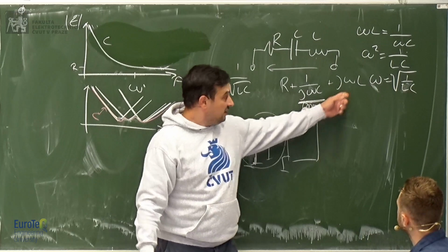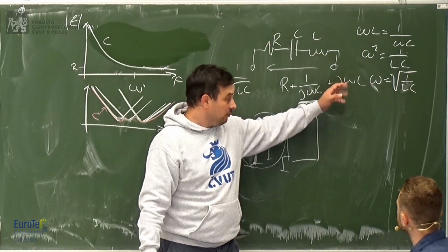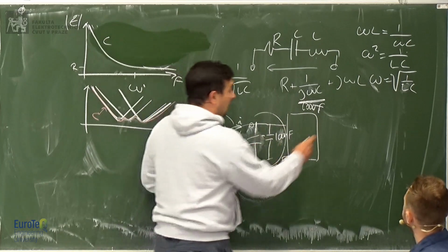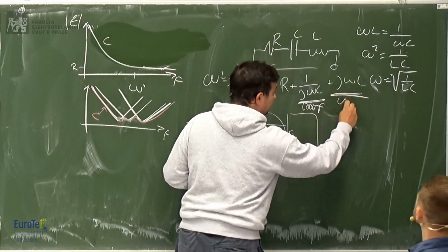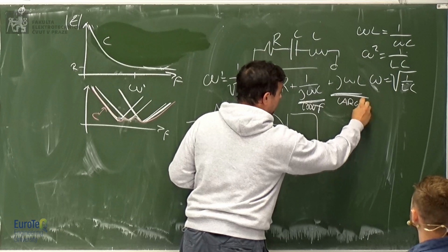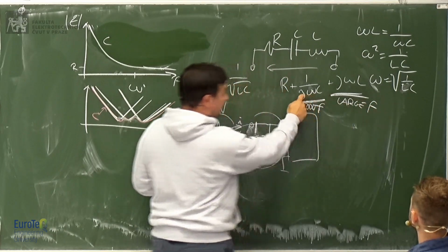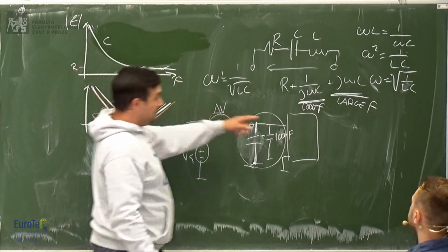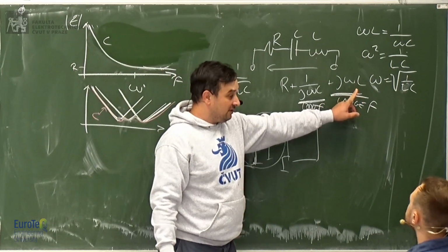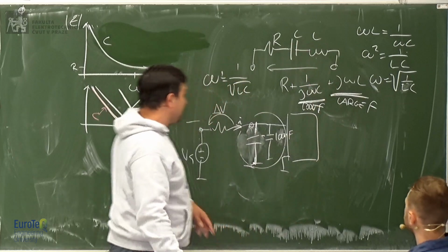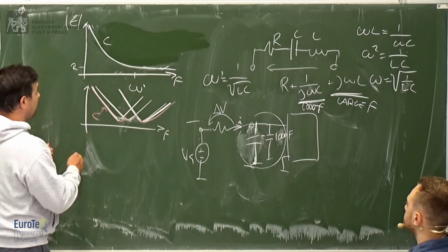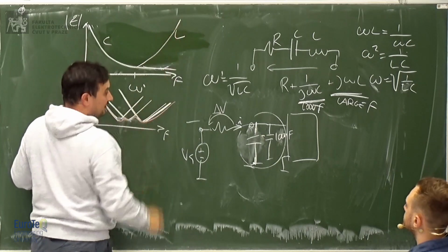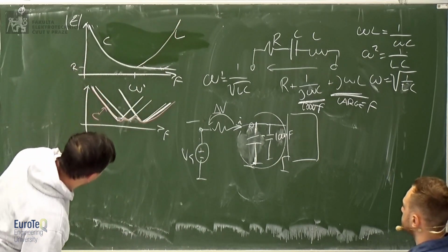So this is negligible, very low. This is very big. So at low frequency, this dominates. At large frequency, this becomes 0, which is what you want. But unfortunately, there's still also the inductance, which spikes up. So at high frequency, the inductors spoil everything.